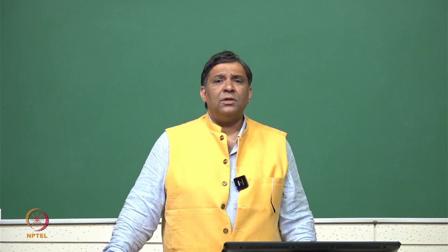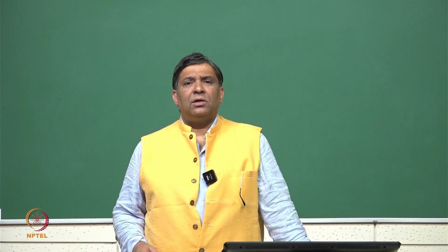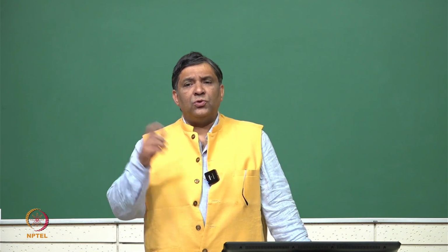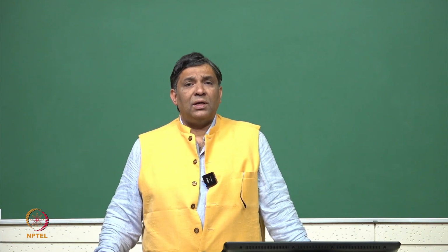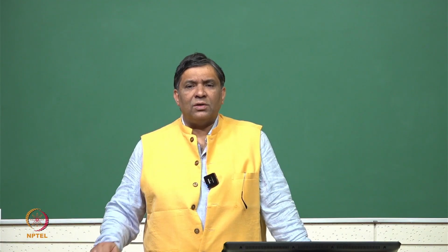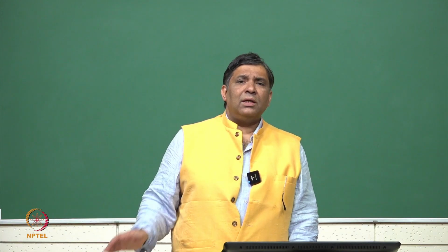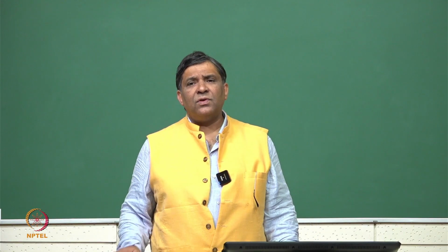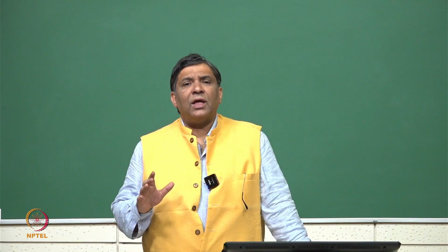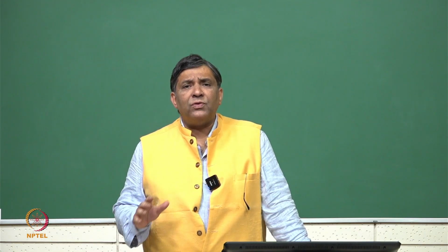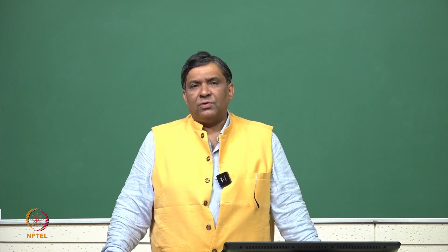This is what we have discussed, and work function is basically the energy required for emission of electron through the surface, crossing the surface binding energy to the vacuum. Okay. And if the work function of the material is less, the emission is better. Okay. Apart from that, also there are some other important properties of material which decide a good thermionic emission process.